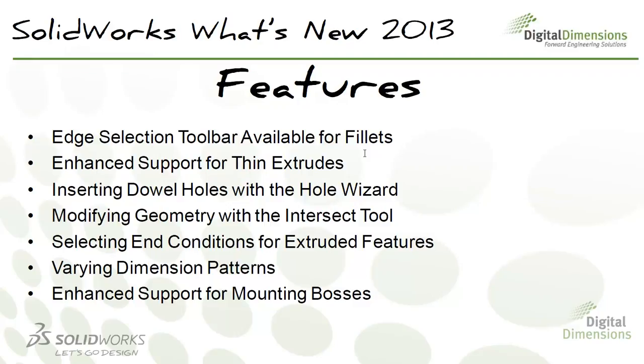And lastly, I'm going to go over the new enhanced support for mounting bosses. You can now have fastener type bosses where you have a head side and a thread side. Before it was just a pin and hole, now you actually can have fastener type head and thread side bosses. So I'm going to go over SOLIDWORKS and show you this functionality.